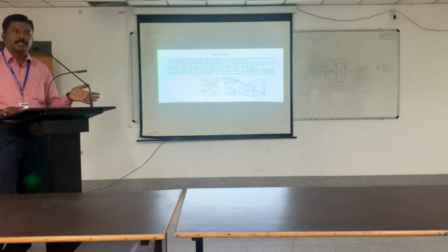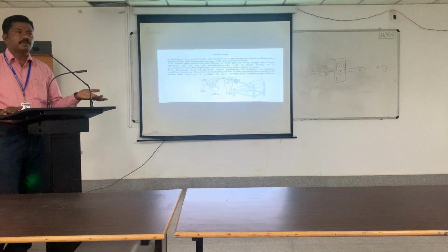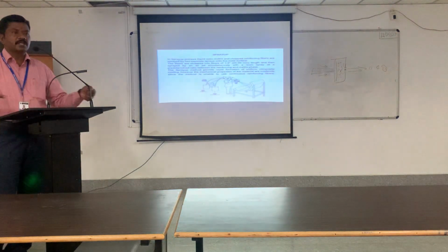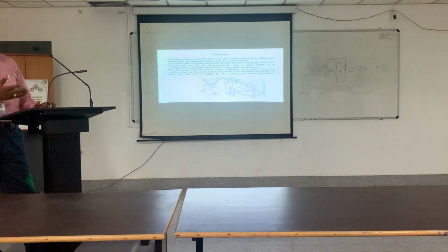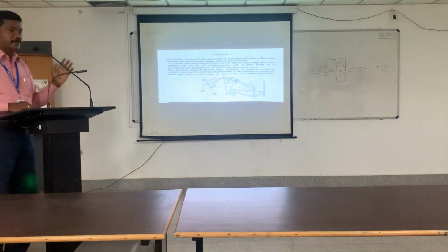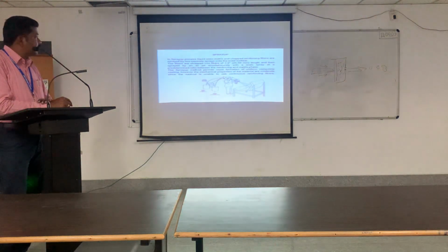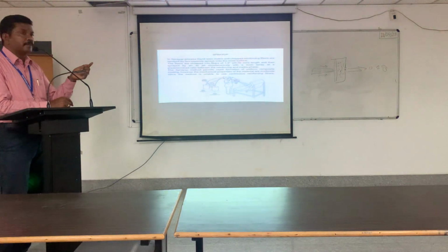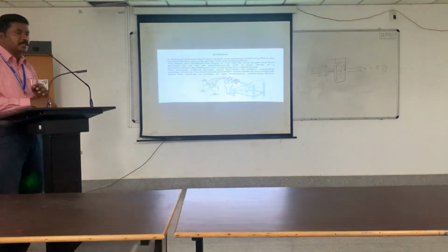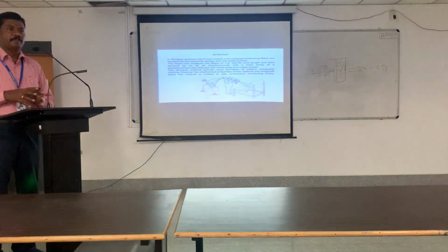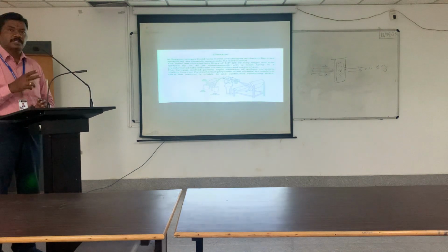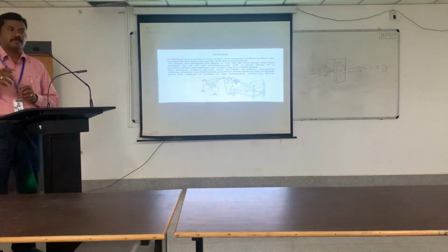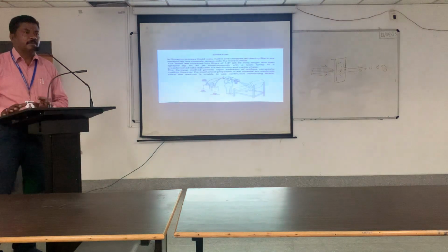So the strength of the composite will obviously be lesser. Since you are not using continuous fibers, short fibers will not give good strength. So wherever you need lesser strength, we can select the spray method. Here the maximum fiber length may be 1 to 2 inches, 25 mm to 50 mm maximum, sometimes even lesser. These fibers will be mixed with the matrix material, the reinforcement fibers cut into smaller pieces, and the whole thing can be sprayed on the mold.